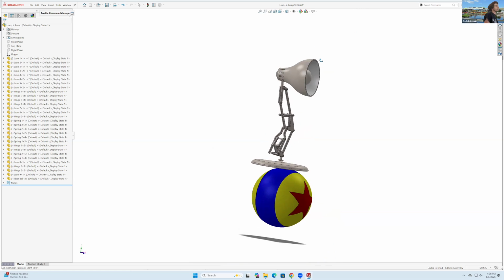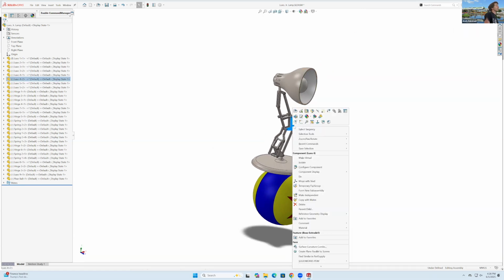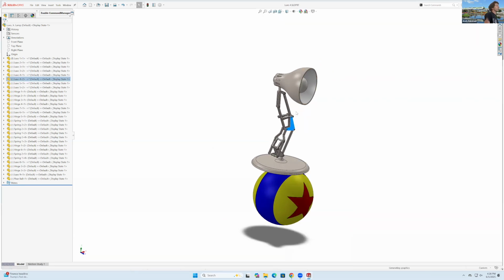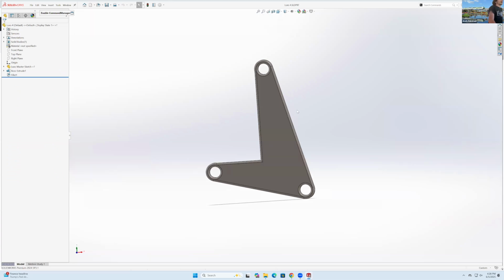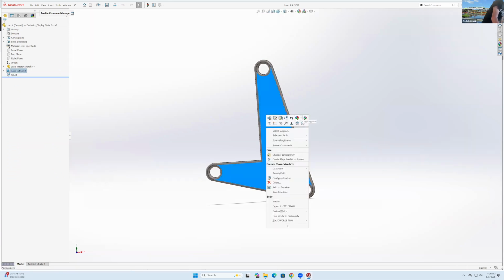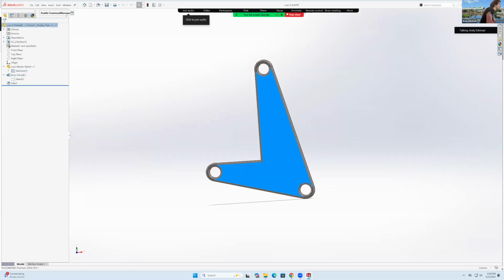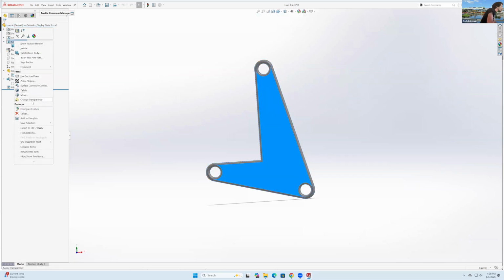Find material properties with parts. Make them solids that pass through each other or give the spring a force constant. I think you can. For instance, if I right click here, in that box, if you click in here where it says solid bodies, right click, there should be somewhere that says material properties. You definitely can do FEA if you want in here, finite element analysis. You can do vibration, statics, where you apply a load.